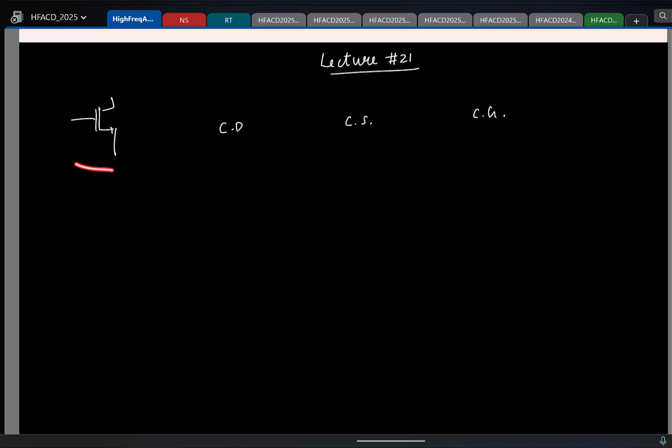And if you recollect, we also saw that we can bias the transistor to be in strong inversion, that is the normal saturation region, or in weak inversion. So in which region do you get the maximum gm? Strong or weak inversion? In weak inversion, we get a higher gm by ID ratio. But why do we generally prefer strong inversion? In weak inversion, the sizes are usually very large because you want small VGS minus VT, and the currents are also small. So small currents with a larger parasitic capacitance reduce the speed. That's why we prefer to operate in strong inversion, typically for speed.